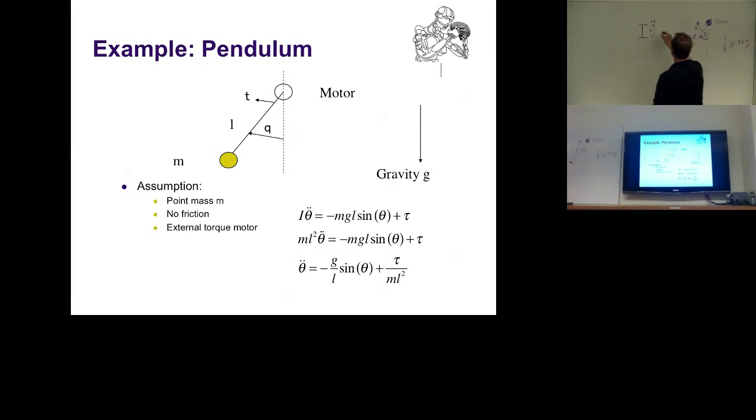A very simple external torque is obviously, I have to equal this, the torque which I'm applying here from the outside. By the way, we need some convention, what we call positive and negative when it comes to torques. And there is what is called the right hand rule. Very simple. You take your thumb, you stick it in the direction of your positive rotation axis, and then your fingers curl in the direction of a positive torque. So if you look at this, we basically have an arrow in this direction, so actually our thumb has to stick into the whiteboard, and we have to curl in this direction, and that is going to be our positive torque. So we define this here actually as positive, importantly.